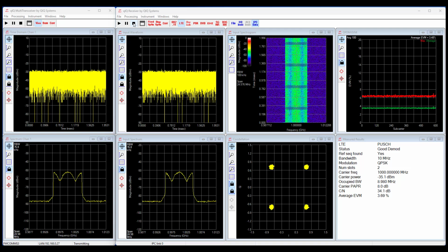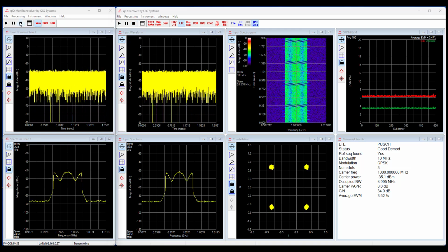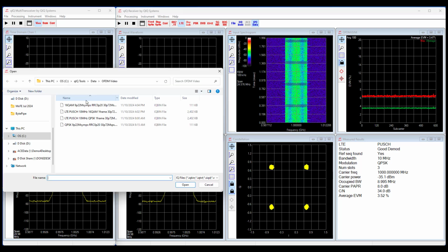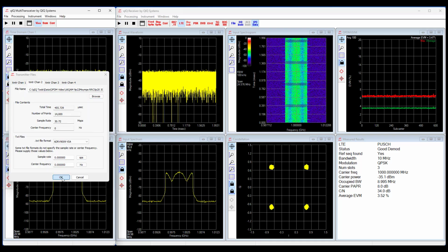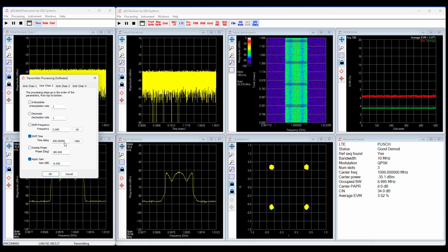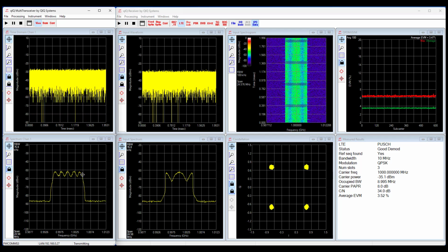For our final test, let's stop these signals playing. Let's bring up a 16 QAM type of waveform, regular PSK QAM type of signal. So here's our 16 QAM. Here is the other one doing exactly the same signal. And let's start that playing. And now I think I'll go 500 nanoseconds of time delay and maybe 10 dB down multipath signal. So now you can see the ripple pattern is even tighter, and that's because we did a longer time, which means a tighter frequency across the spectrum.